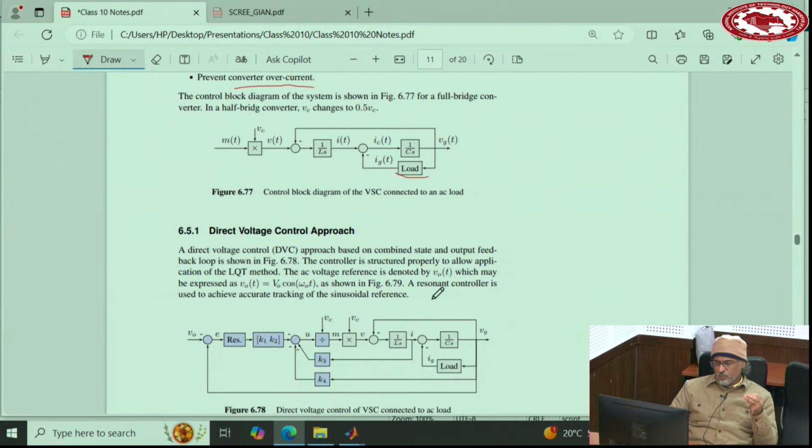Now, normally we don't consider load in our control designs. If you have good information about the load, you can consider that in your design. If you don't have it, just completely ignore it, and look at IG as a disturbance. Remember, we just did the same thing for PV, and we said if the controller is strong, it doesn't really mind. It will be able to tolerate it. So if you don't have much information about the load, or you don't even want to bring that information into a study, you can just completely ignore this load and consider this point as a disturbance.